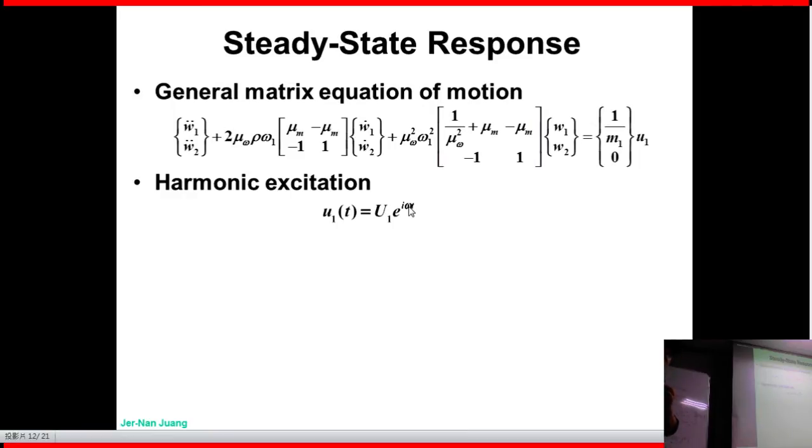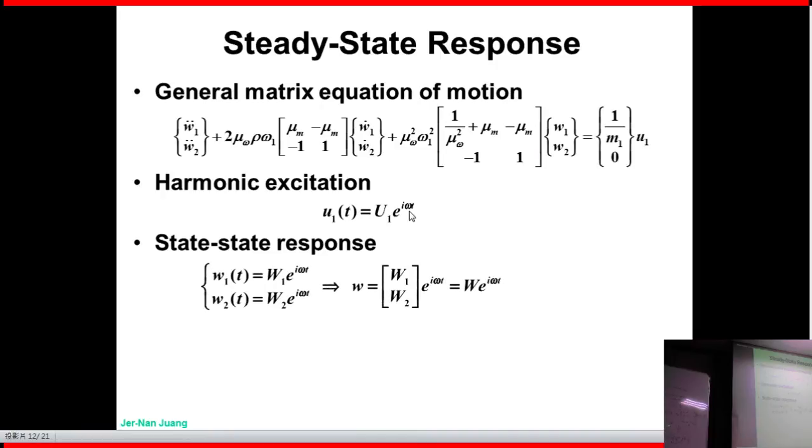So above 15 hertz, you don't worry about it, because the Taiwan earthquakes in the past 100 years were really less than 15 hertz. But how about wind? Wind is maybe about the same, less than 15 hertz, or even lower than that. So that omega is the dominant frequency we're supposed to get.